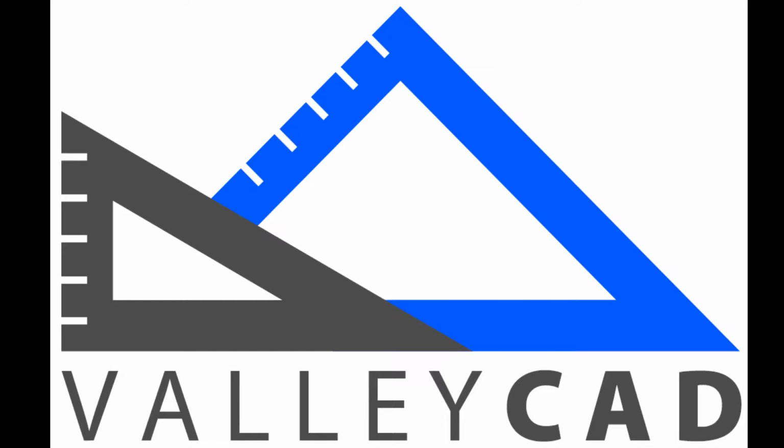And for today's Take a Thought Thursdays, we are going to be looking at some custom key bindings, actually. And you'll see in some of my other videos that I do where I can quickly switch views from front view, top view, right side view, top view, and so forth. And so I wanted to show what I'm doing exactly so that I can switch between those views so quickly instead of having to click on the 3D icon in the bottom left corner to switch views or push spacebar and specify my views. So let's go ahead and take a look at that.